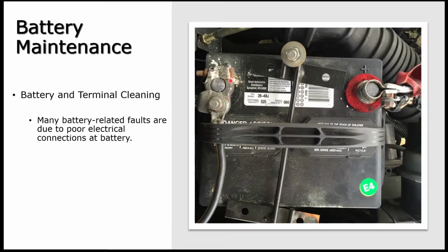It's rotted out. It needs to be replaced. Okay, many battery faults come into the vehicle. In today's cars, we have fail codes that come into play. Fail codes will identify potential electrical issues, and we'll learn more about those, especially when you get into advanced electrical and engine performance, things of that nature. But fail codes can be generated simply because we have a bad terminal connection.